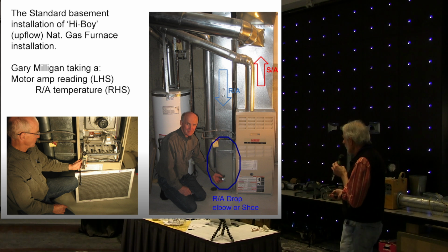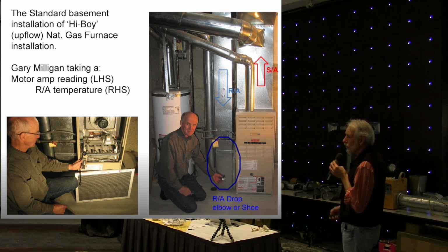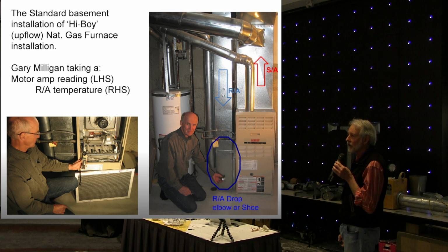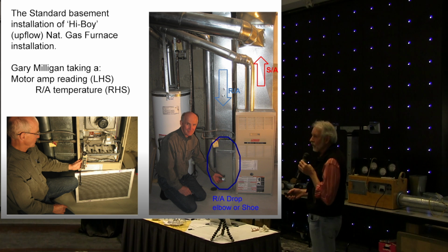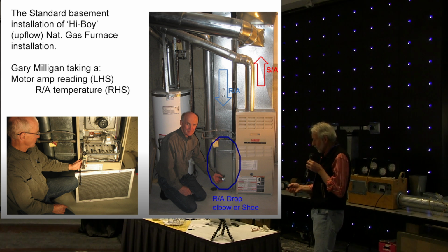I'd like to zero in on this return air drop because a good part of my discussion and this model is going to be focusing on that return air drop, because that's the biggest villain that we face today in this province, absolutely universally throughout all gas, forced air, and heat pump systems installed in this province.